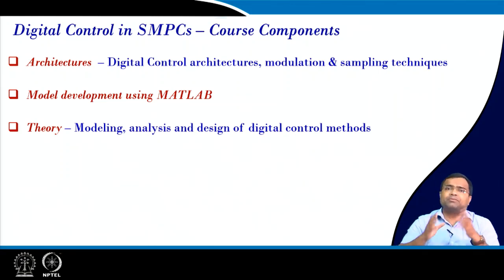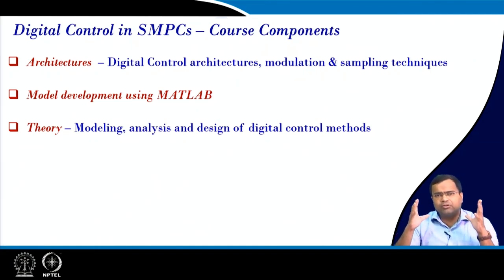Then we will show how far this modeling technique can capture the behavior. For example, in our previous course on control and tuning methods, we learned that with a small signal modeling technique, if we get the linear transfer function model, obtain the step response, the AC coupled response, and add the DC component, then compare with the actual switching simulation, the model reasonably captured the behavior up to 1/10 of the switching frequency, and beyond that the model starts diverging. But in this course we will show such a model may not even be sufficient for digital control, even under low bandwidth.